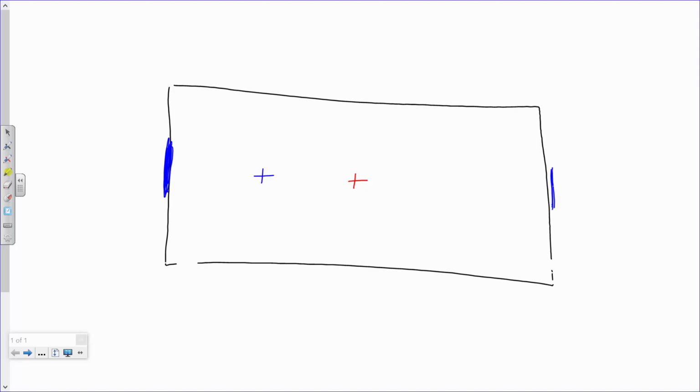Does that make sense? So what happens is when I take a wind and I hit the building, just because of the location of where the center of mass is and where the center of rigidity is, the building's going to twist, whether I want it to or not. Now, if you're looking at this example, this rectangular building, you're like, why the heck would you put a really strong brace on one side versus another? You'd probably be right. There's no reason to do that.